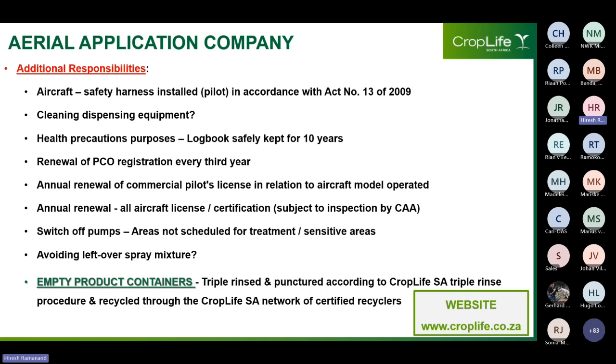Pilots, whether employed by an aerial application company or where the aircraft is rented, must always remember to switch off pumps when flying over areas not scheduled for treatment, and in particular sensitive areas. In order to avoid issues with leftover spraying mixture requiring disposal, pilots must ensure only as much product as will be needed at one time for a specific application is prepared and will be applied strictly in accordance with the